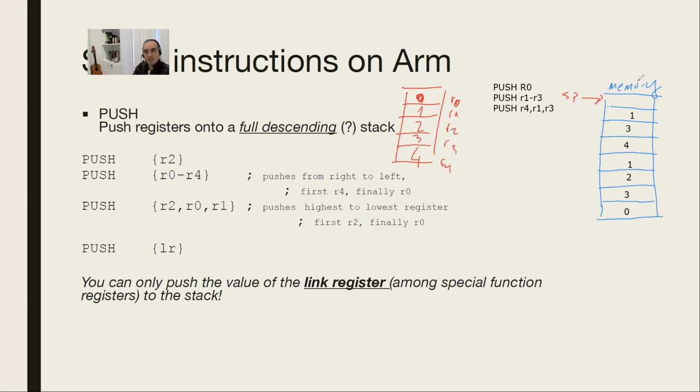Guys, this is memory, not the instruction memory. Be careful. Instruction memory is where the lines of code are. Memory is where your data is. So this push instruction can automatically write things to memory. Previously, I told you if you want to write something to memory, you use STR. That was correct, but STR cannot write to that dedicated stack location.